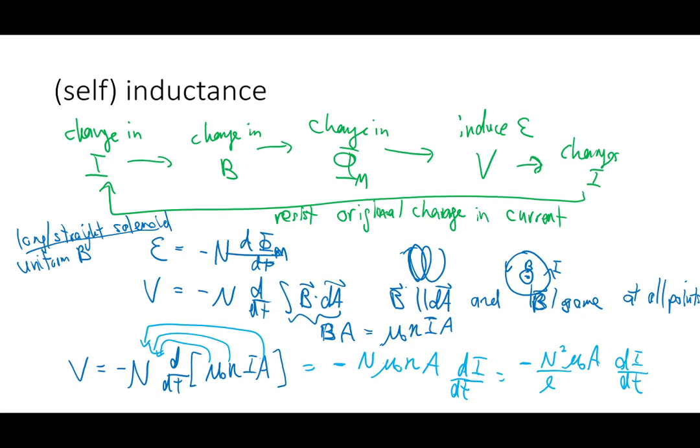Like that. And now we have an expression that relates two things we often measure in circuits: voltage and current. And everything else, there's this big chunk in the middle that looks kind of messy, but that's not expected to change in time. It's given for a given shape, size of coil. So very much similar to what we did to capacitor, we just kind of put a big box around it, and we call this thing inductance. And we're going to use a symbol L to denote inductance, because I guess we can't use I, it looks too much like a 1. And the unit is measured in henries.